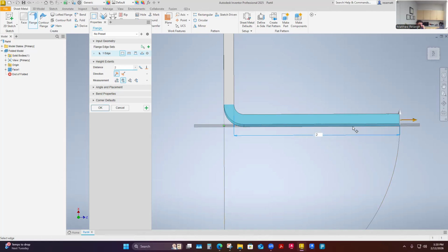inch dimension that's holding. So what this does is one is going to be a shorter overall dimension than the other, in terms of necessary material to make that bend. And what we have going on is some compressive forces on the inside radius smashing that steel, and some stretching of material around the outside radius.